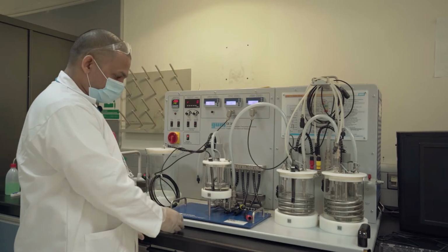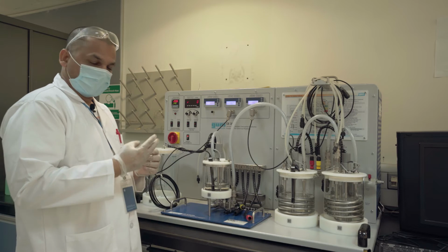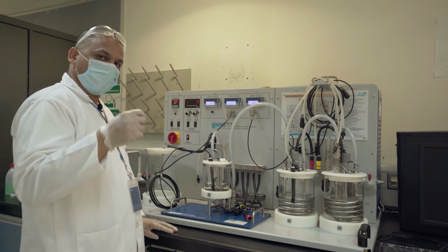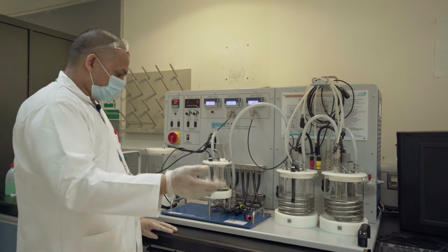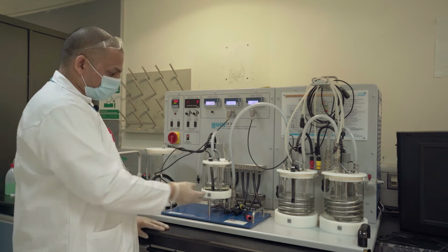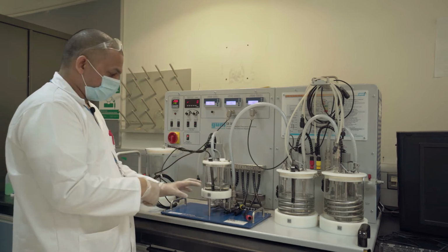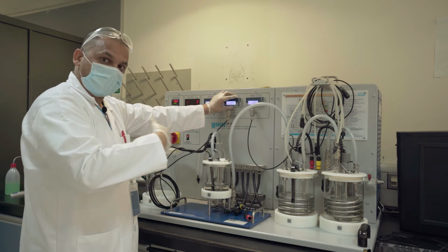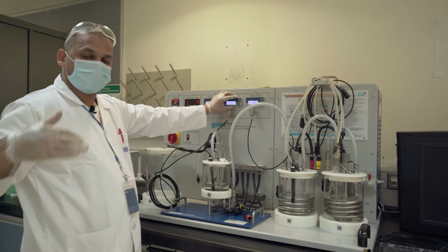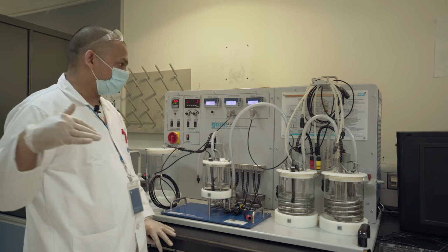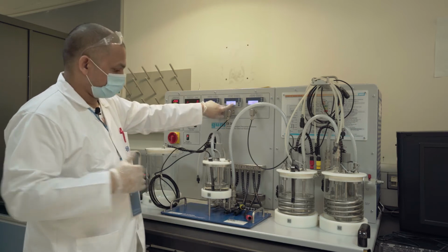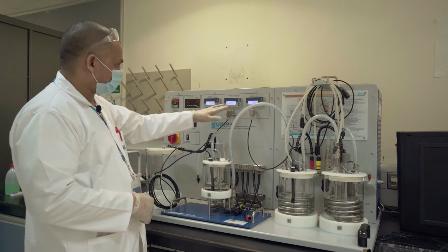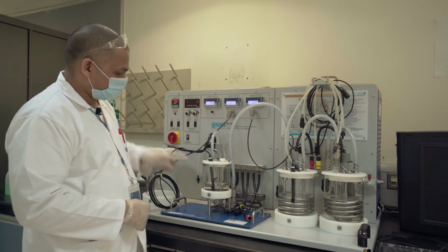We have the batch reactor here first. So what we do, we take two equimolar concentrations, which is 0.1 N NaOH and 0.1 N ethyl acetate. Both of them we move here and then allow them to react. So what will happen? Initially the concentration is high, so the conductivity will be high, and as time progresses, conductivity will go down and stabilize once it has reached equilibrium. Right now I can see this one has stabilized around 0.1 millisiemens per centimeter. So this is my final conductivity.